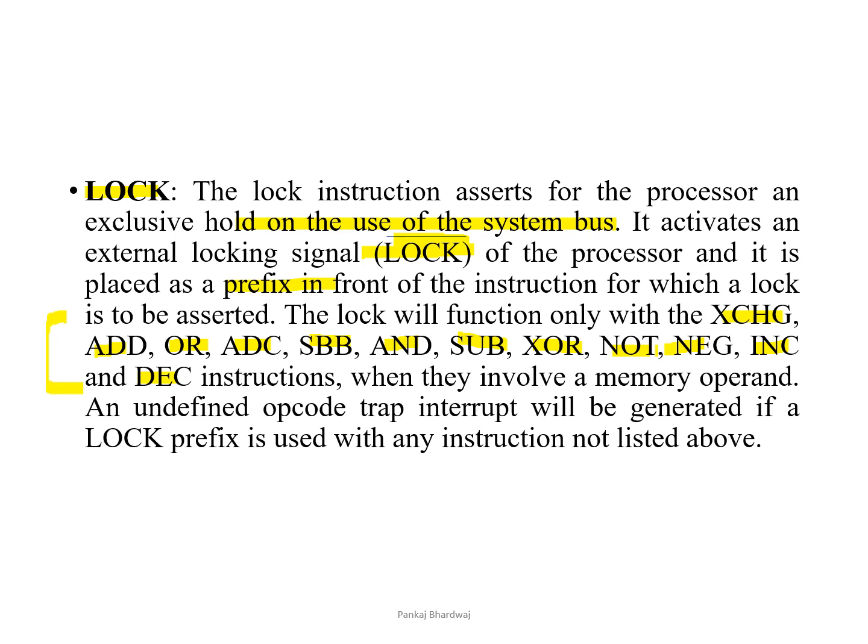If the lock prefix is used with any instruction other than these arithmetic and logical instructions, it will generate a trap interrupt.